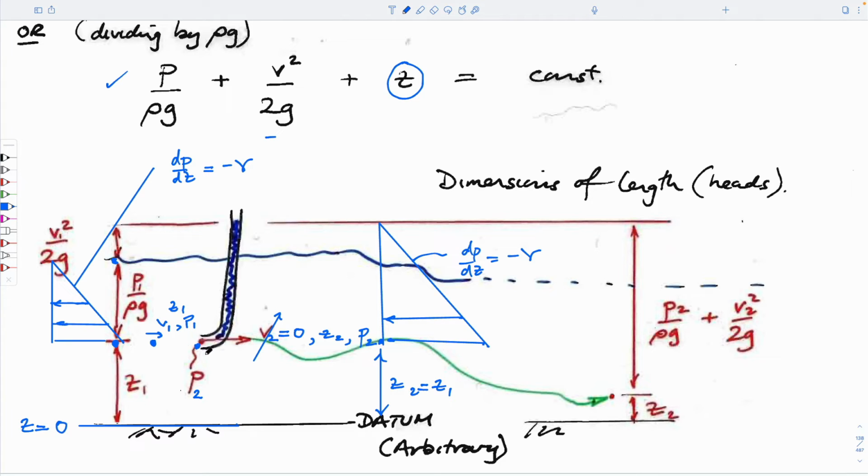It means that you're able to measure the pressure. So the idea of a pitot tube is that it has a point here, and it measures the pressure at this point inside it. It has a second concentric tube where it measures what P1 is on the side of it. And from knowing the magnitudes of P1 and P2, it can calculate exactly what this term here is. Velocity. That's how it works.